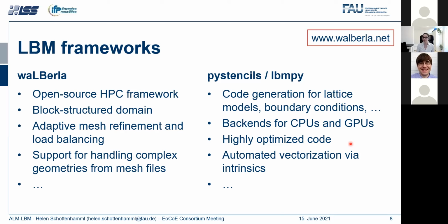The two of them are Python packages, which we also develop at University of Erlangen. Normally, you would use them in a standalone method, but we use them to generate code for waLBerla. So now you can think of the collision operator; I did not give details on how it looks, but there's a whole slew of collision operators that you could use. The same holds true for the boundary conditions, for streaming patterns, for communication patterns. And if you want to handwrite everything from scratch and do the optimization for different hardware, this is cumbersome, not feasible, and you just don't want to do that. So that's why we chose to use code generation for that.